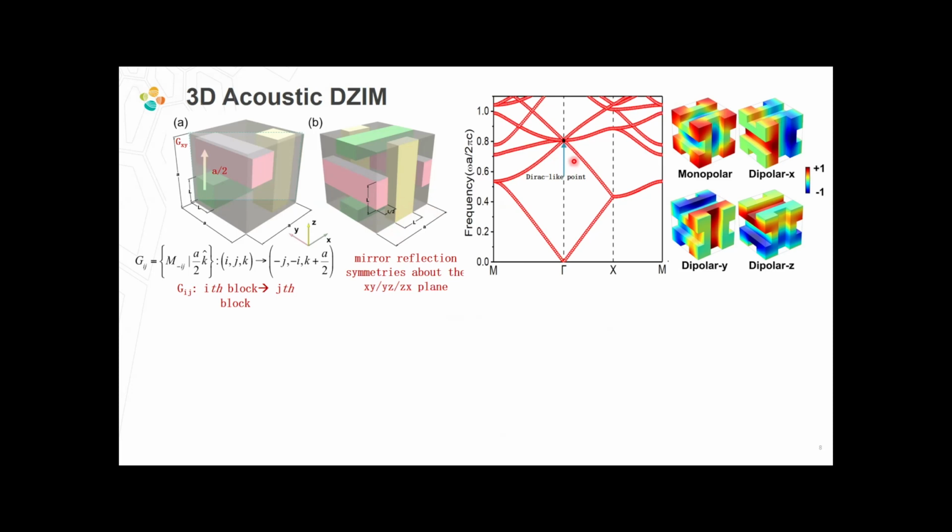For this structure, we cannot apply the effective medium theory that we derived 20 years ago, because that is for isotropic scatterers. For this complex unit cell, we developed an effective medium based on the single mode approximation. We read out these eigenmodes, did the field average, integrated the field on the boundary, and then took the average.